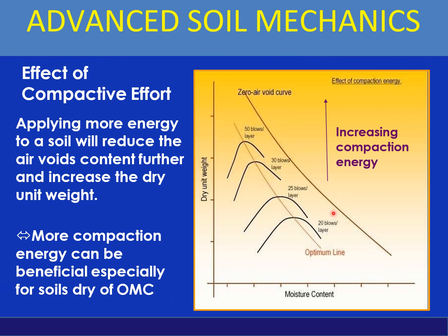So you can see that here you are having the different curves, and you can see that with increasing compaction energy, your curve is moving in the upward direction. And here you can see that the maximum dry unit weight has been achieved.